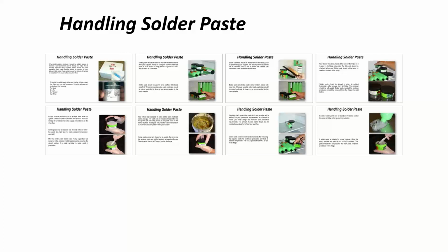So that's the basis of what you do, but each different manufacturer may have slightly different recommendations on paste, so it's important to understand what they require. And of course, more recently, some manufacturers have paste that doesn't require fridge storage at all and gives you all the longevity of a paste without doing that.